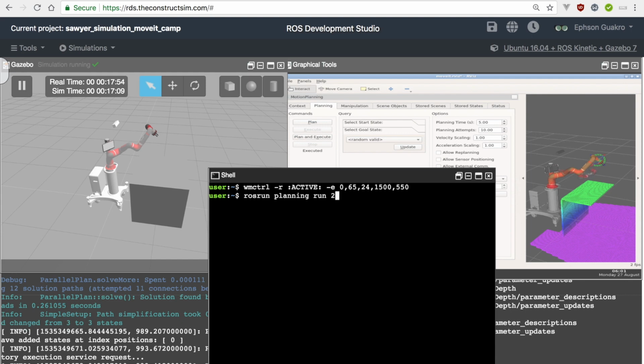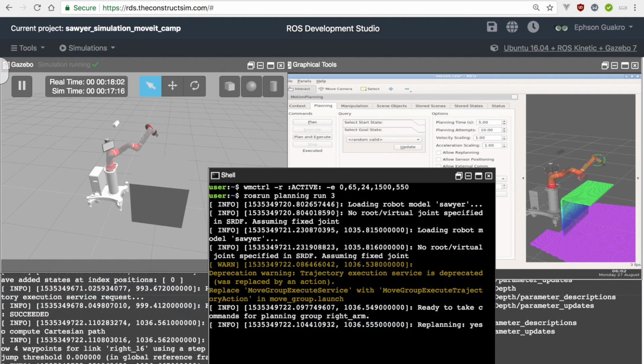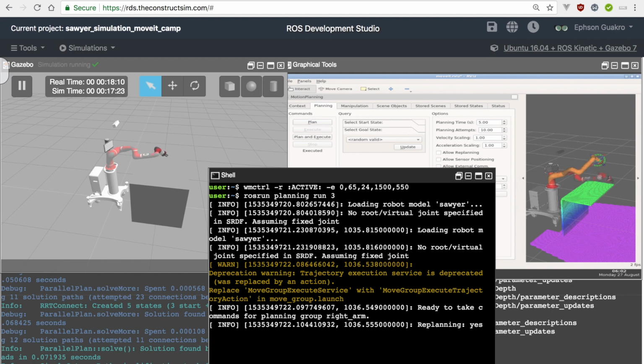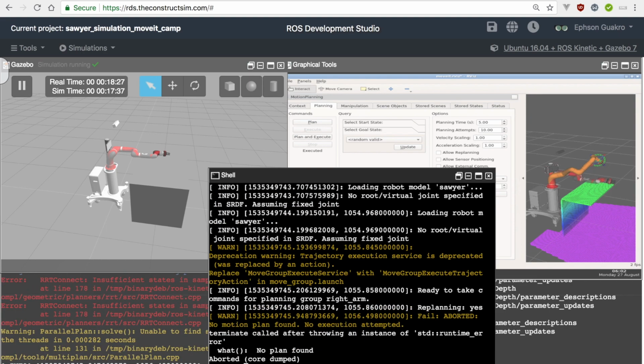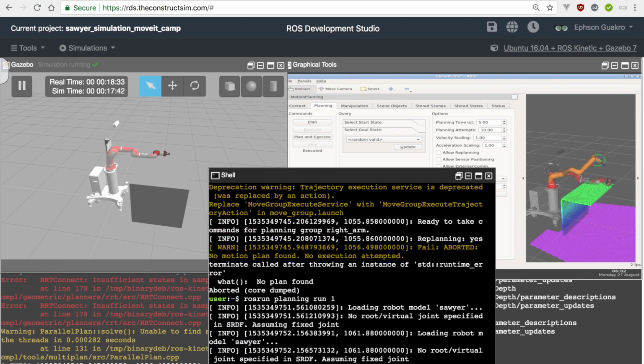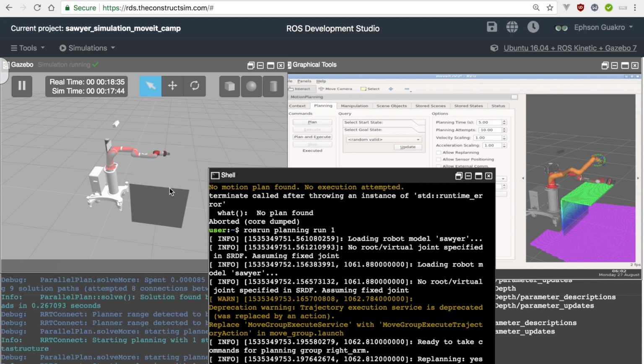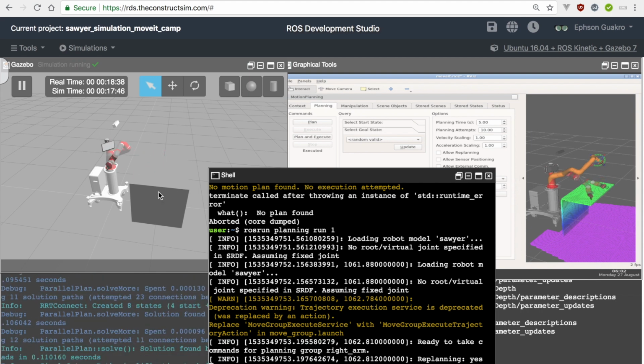So here we can look at some of the planning that we used from last session. For example, we had planning number 3, which I think is the Cartesian path. No, this is actually the Cartesian path, which is mainly recommended for when the end effector is approaching its final goal. Yes, and then we have number 2, which I think is the joint states rather. Okay, our planning failed, it couldn't do that. Let me try 1 and let's see. Okay, hold on. Oh, it worked.